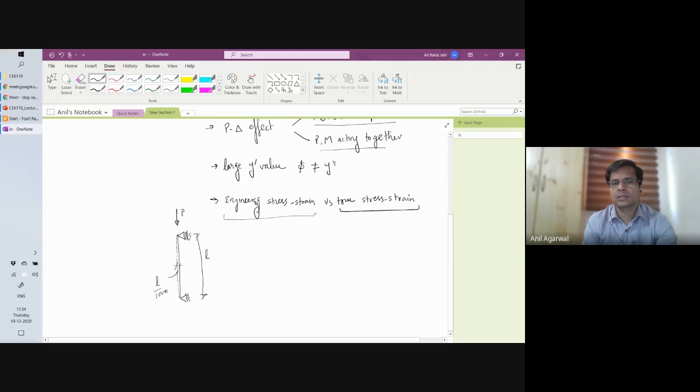Then this load P is supposed to be resisted by load P here, or the reaction here, with perfect alignment. But if I draw the free body diagram of half of the column, and I'm exaggerating and amplifying the imperfection here, so this is whatever L by 1000, let's say. This P has to be applied here, right? This is how the P must be coming in. And this is the free body diagram of this part. So the two P forces are not aligned.